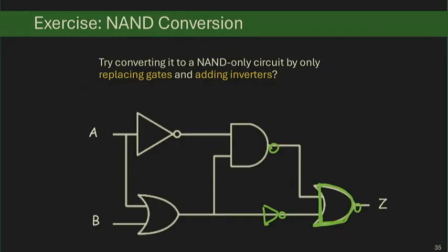And the OR gate can be viewed as something sitting by itself, and you can convert that into a NAND gate with two inverted inputs. And essentially, these two inverters will just be represented as inverters. And now you have a fully NAND circuit. And of course, these two inverters over here and over here can also be combined into a single inverter. So rather than drawing this inverter, you can create another branch after the inverted A line and then connect it to the bottom.